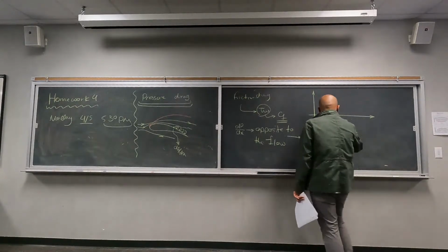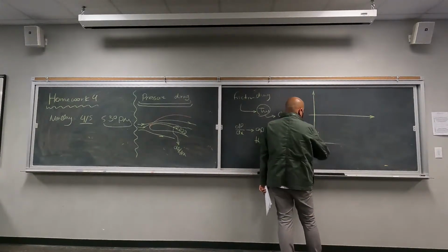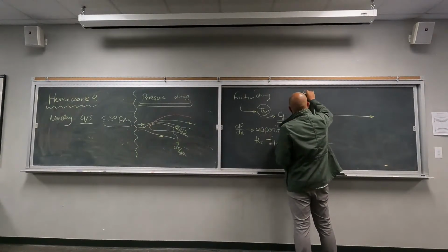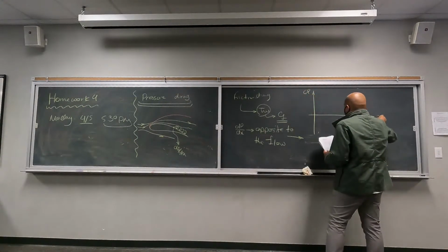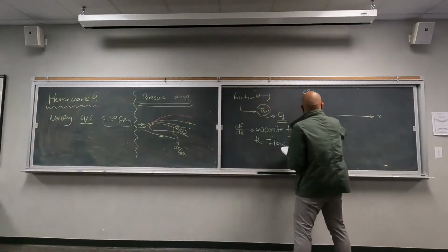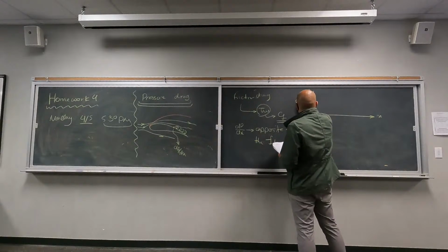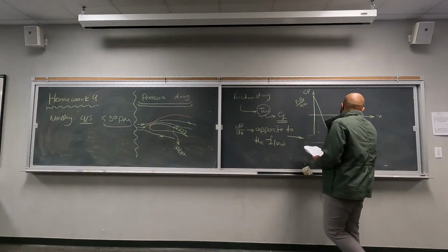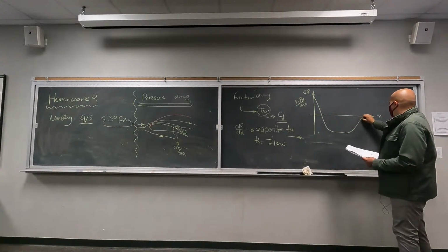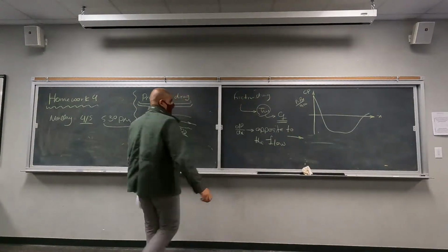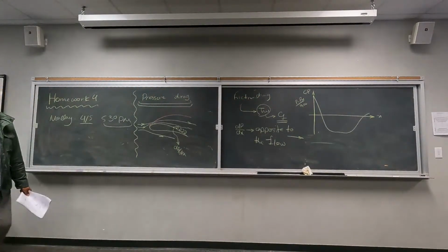Let's take a look at the pressure gradient with respect to x. This is the pressure coefficient, on top of the airfoil. We start with a very high value, (P minus P infinity) divided by Q infinity. That's your pressure coefficient. Then it goes to a minimum location, and then it comes back up, to a positive value.